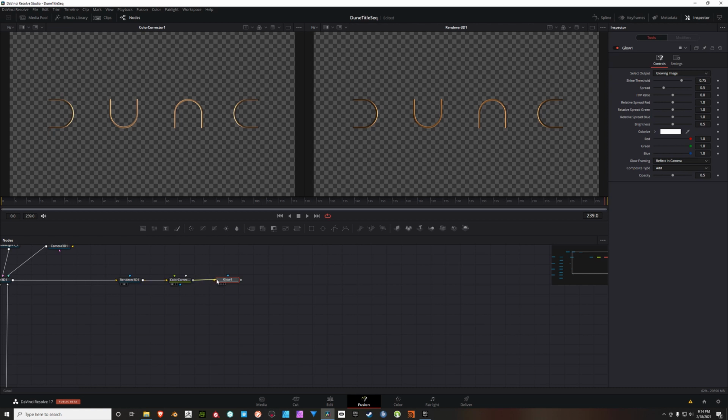And I'm going to connect that to the node. I'm going to hit 2 on the keyboard so we can see what it's doing. And under the glow node, I'm going to change the output to shiny regions, okay? And the threshold is going to be 0.378, all right? Now, that really darkened it, but it did help with some of the metalness that I was looking for.